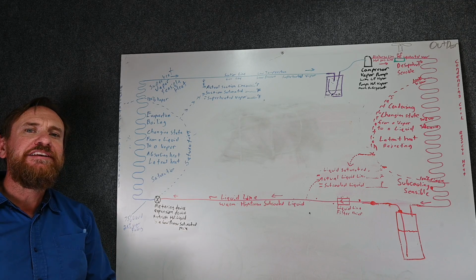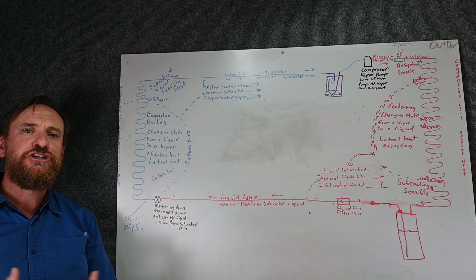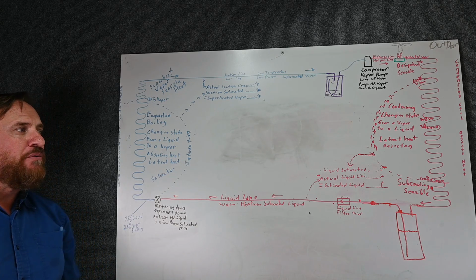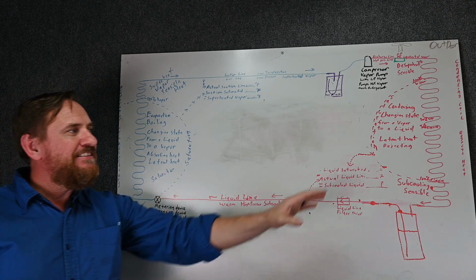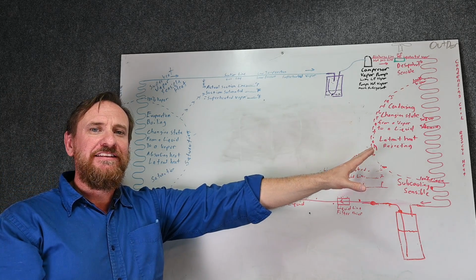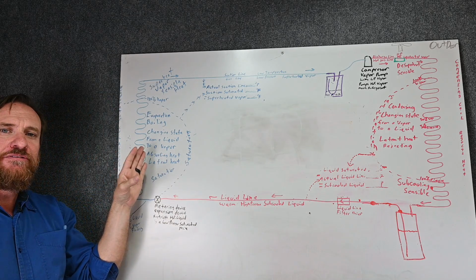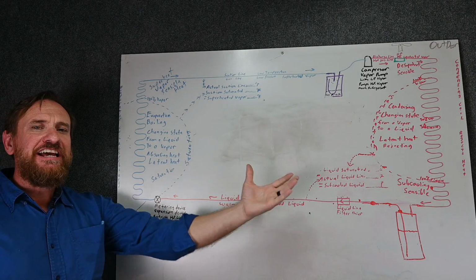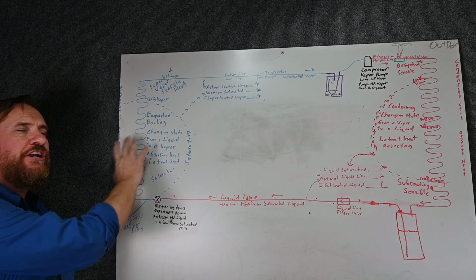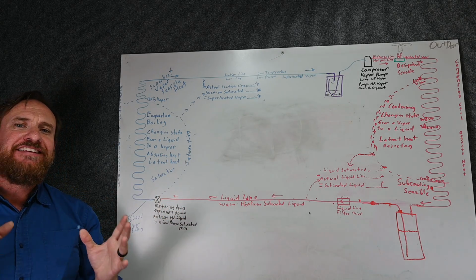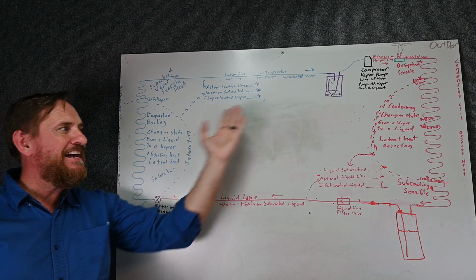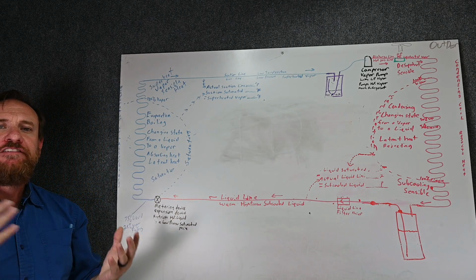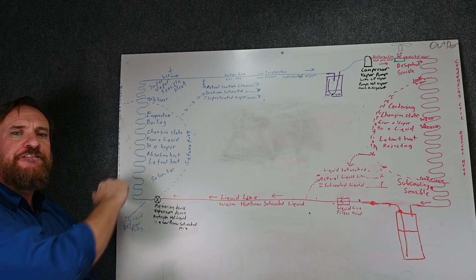In the field, you're going to hear people talk about what pressure should be. There's only two ways I know of to find out what pressure should be. The first way is when they test equipment. They have a set condition that they test all condensing units at, and a set condition temperature and humidity of all the indoor conditions. At those set conditions, they end up with what they call a 40-degree evaporator coil. Under these laboratory conditions, we know exactly what the outdoor pressure will be and exactly what the indoor pressure will be. And with a variety of different refrigerants, it's usually still at a 40 degree.